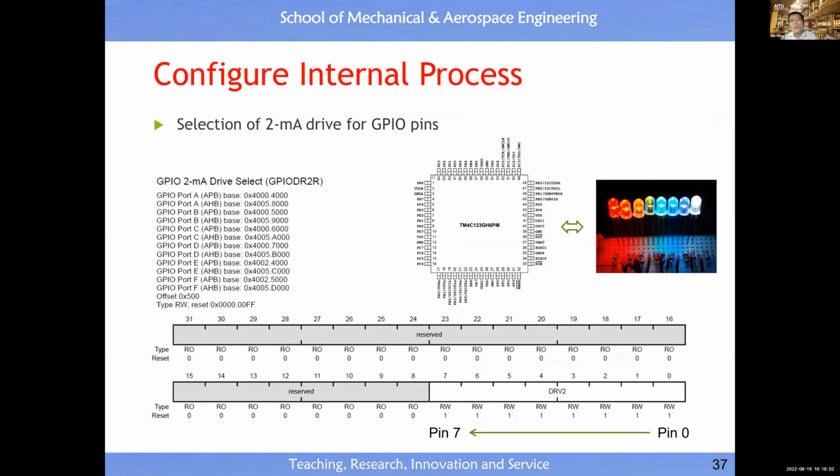Another thing: when you operate your motor, sometimes you want to know that you have turned it on. How do you tell the user this motor is on? It's always good to light up an LED. The good news is that this pin can serve as a current supply. You can connect an output device which doesn't take action but just indicates the status, like turning on an LED light. You can supply a current of 2 milliamperes.